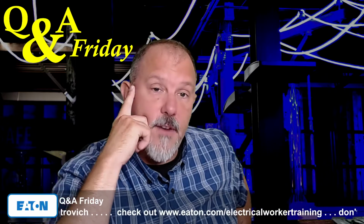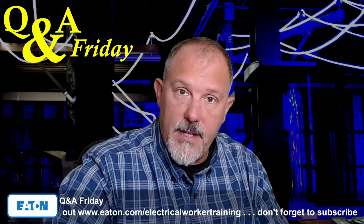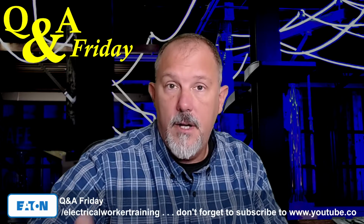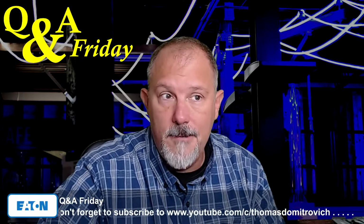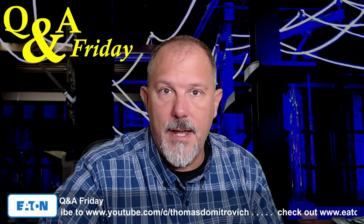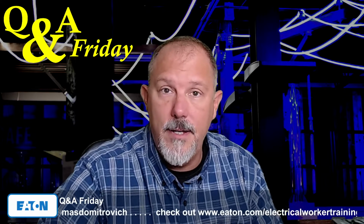I think it would be hard to find, if you had a cord and plug connected device and you put a GFCI receptacle in that outlet and you're supplying a cord and plug connected tire inflation machine, you would be hard pressed to find an inspector that would say you're not providing GFCI protection for the outlet because you put a GFCI receptacle in it. It became a receptacle outlet and it has GFCI protection.